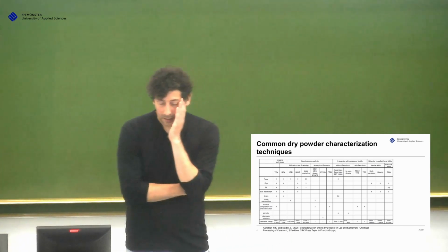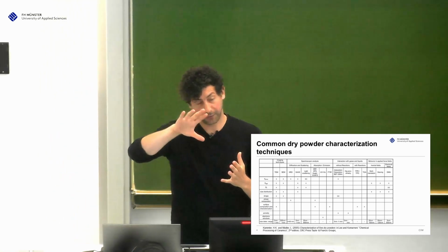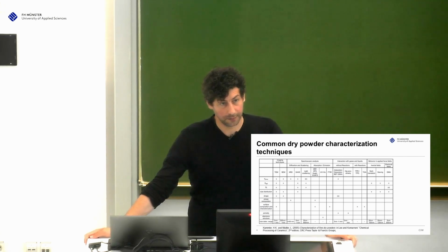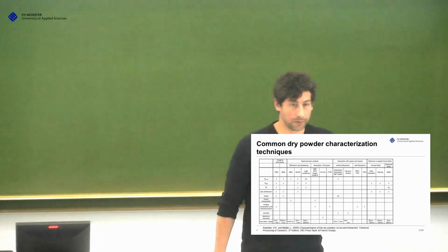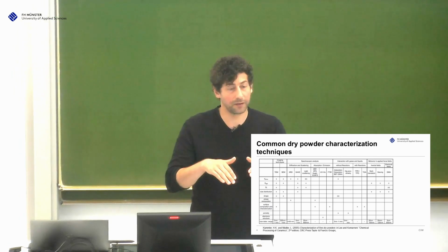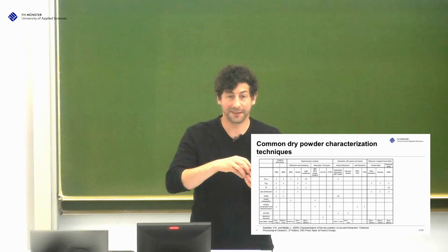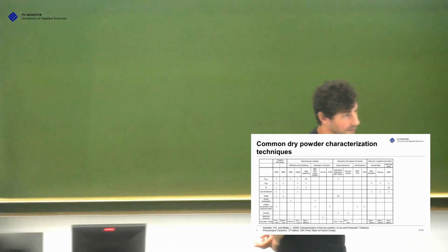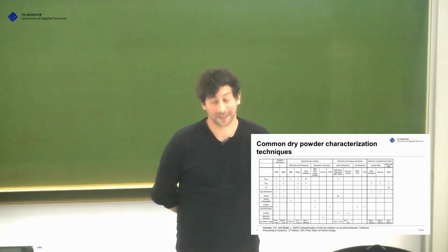Yeah, so the nice thing is basically, as you said, you heat your sample and then you see the mass going down from the sample. Do you directly know what is leaving your sample from the TGA itself? So you have a powder and you heat it to 100, 200, 300, 400, 500, and you have it on a balance, and after time you see that it goes less in weight, because something, depending on the temperature you apply, is leaving the surface. Does the TGA directly tell you what is leaving the surface? No, why? Yeah, there is no detection about it.